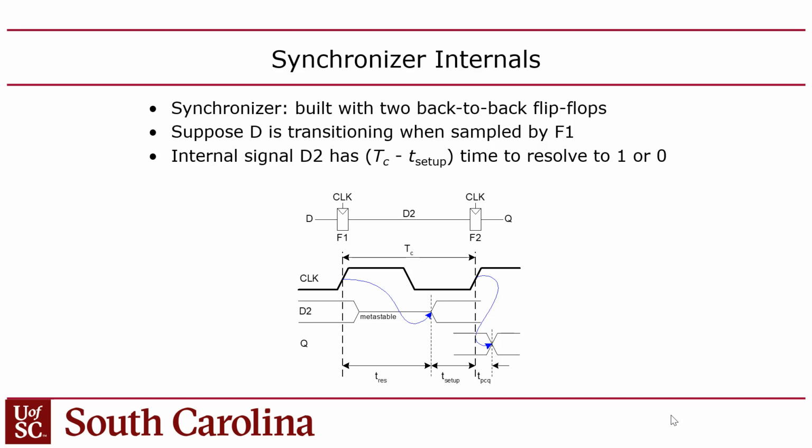So basically you expect the first flip-flop is going to periodically become metastable whenever you have an input wire into a logic circuit. But if you put that second flip-flop in there, you can hope that if the first flip-flop goes metastable, it'll resolve itself before the setup time, and then you'll get a clean output on the second flip-flop. Make sense?